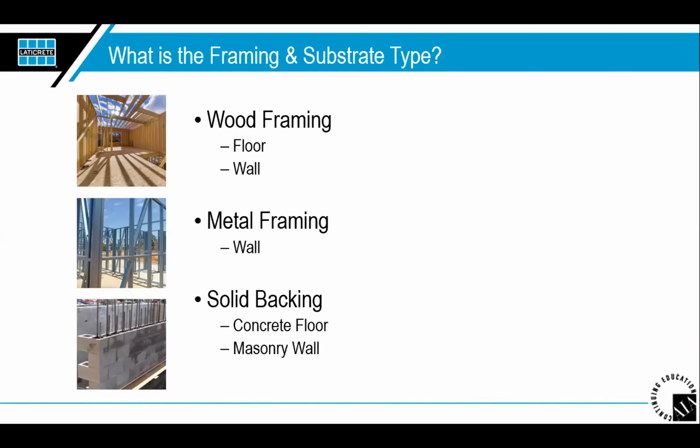We're seeing that on residential applications. There are different types of boards that are being put up now, and most commonly they're using a vapor retarding plastic that's being put over top of it. But companies are out there that are producing or already have produced liquid applied membranes too that can act as a primary waterproofing, or they'll act as a secondary, and in that case, they're widely used as what I would refer to as a bulk water management system.